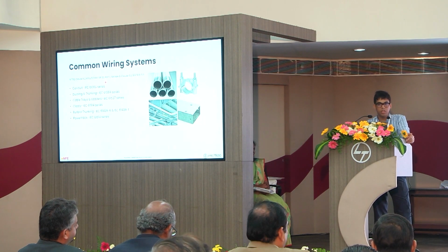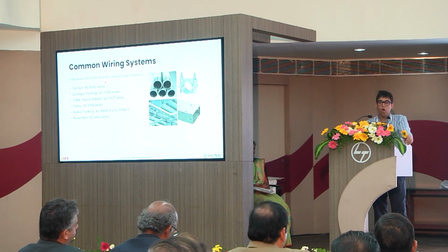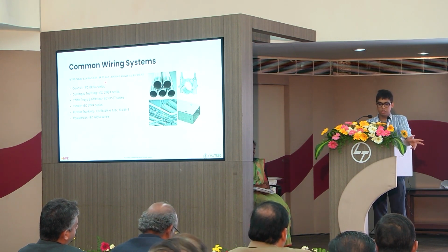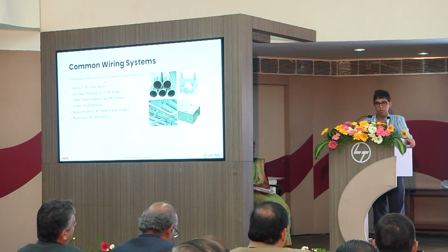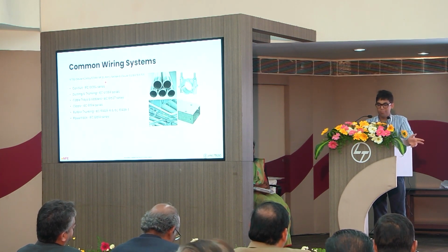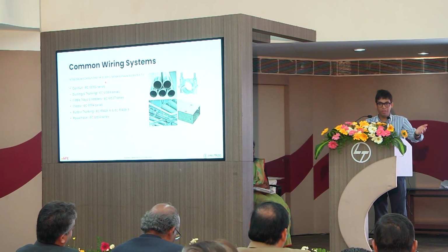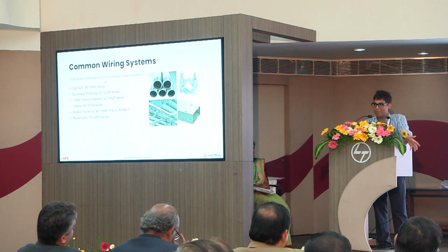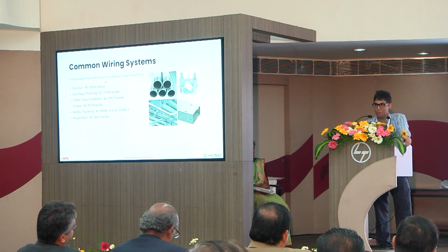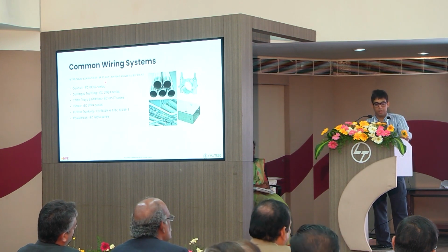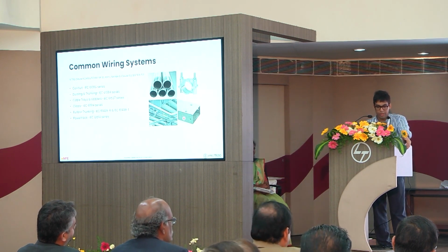Now, a classic example is I was consulting on a site in Mumbai, and they had already run all the trunking before I was involved. So I said, what is the trunking that you have used, what's the brand? And the electrical contractor said Jindal. Now, Jindal is an aluminum manufacturer. They don't have the necessary equipment and they don't run the necessary tests to prove their sections as trunking. So there's no way that that installation could actually comply with IS 732 or SP30. And like Mr. Gopakumar mentioned, then you're non-compliant. So conduit is the 61386 series, ducting and trunking, which is here, is the 61084 series.